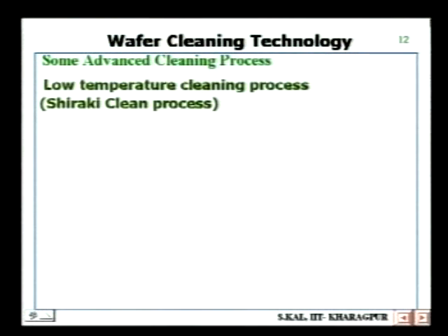You know, if you want to form an epitaxial film on silicon, which is an essential layer for making devices, either bipolar or MOS devices, those epitaxial layers are formed in ultra high vacuum ambient, and at high temperature, in the range of 1100 degrees centigrade or 1150 degrees centigrade.